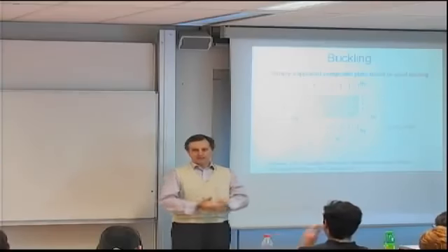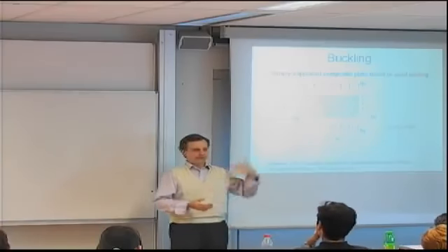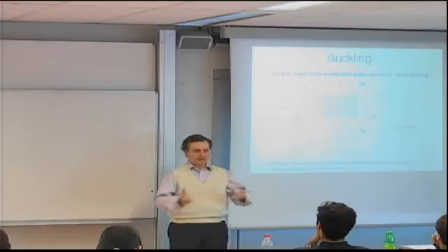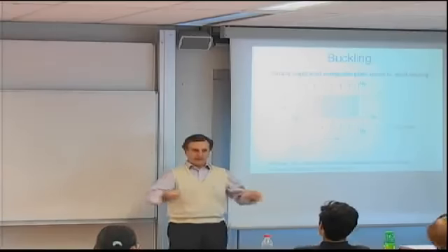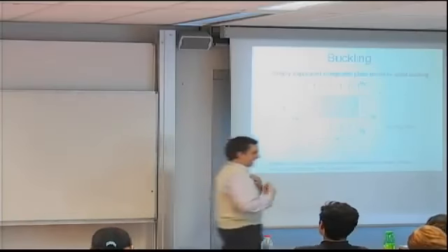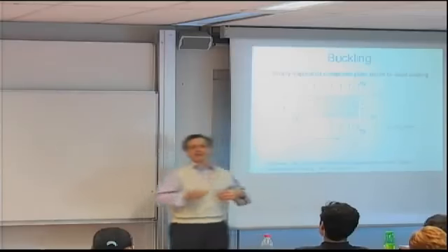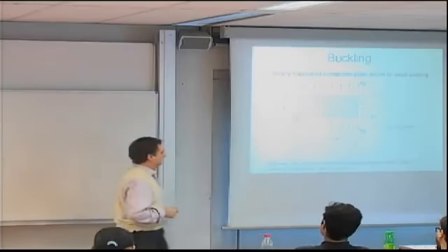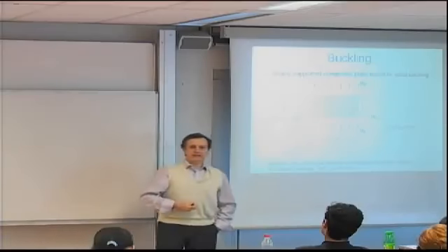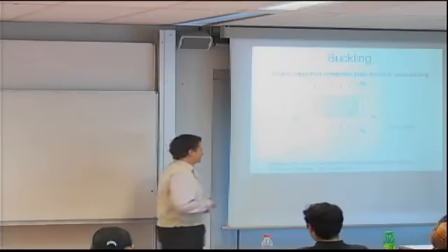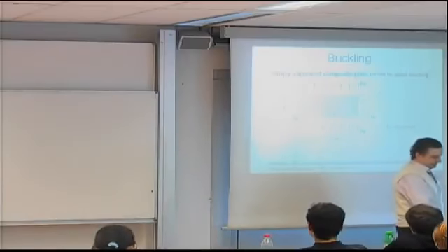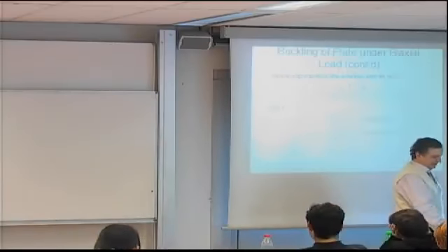That kind of bifurcation, buckling, is not present in a laminate that has a non-zero B matrix, because then at very low loads you will get out of plane deflections. So on the one hand it simplifies our calculations, on the other it actually deals with defining buckling differently if we have a B matrix present. So for now we neglect this, or we assume the laminate is symmetric.